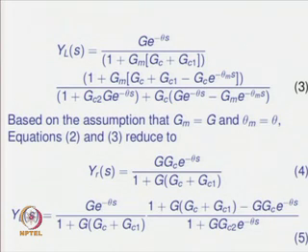What do we mean by decoupling of the responses? One response does not affect the other. Indirectly speaking, the controller you have designed for set point or servo tracking will not be affected by the controller you have designed for disturbance rejection.